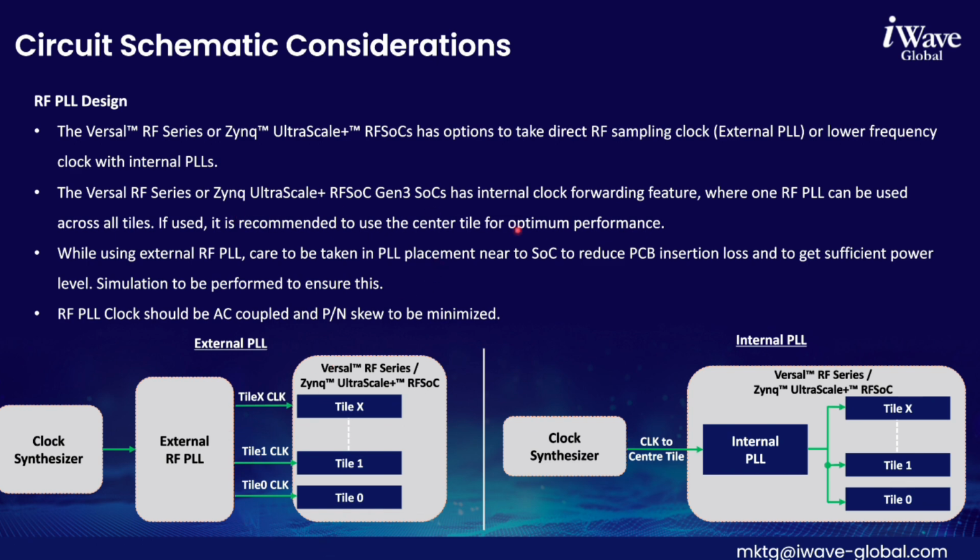But with this internal clock forwarding feature, we don't have to use multiple PLLs. We can give the PLL clock only to the center tile, and it can be internally forwarded to all the other tiles, and still we get optimum performance. This is a very good feature, and it is supported only in RFSoC Gen 3 devices and Versal RF devices, and it is not supported in Gen 1 and Gen 2 devices.